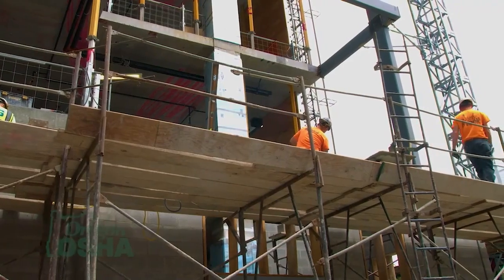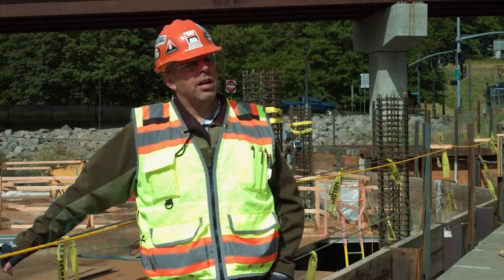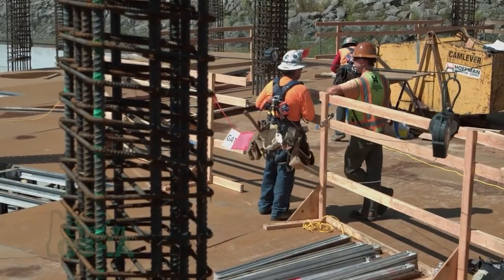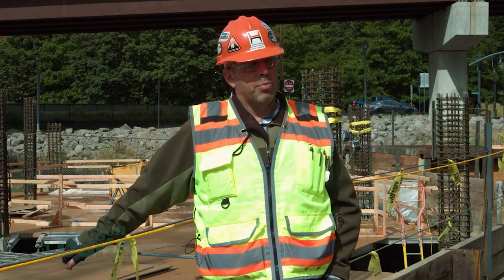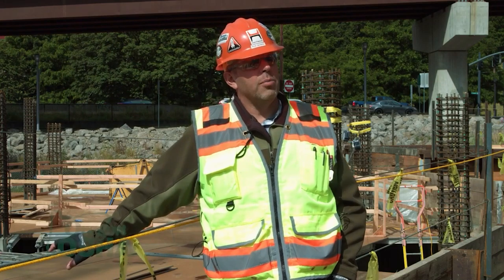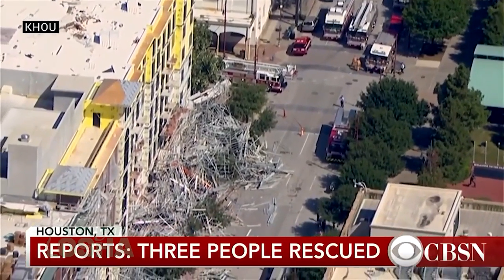You can use scaffolding as a catch platform. I don't do that as often. We will default towards a guardrail system if we can. One of the most important things, paramount in scaffold operations, is proper employee training. And I mean proper employee training beyond just a red tag or a green tag hanging at the bottom of the scaffold. Some of the biggest incidents in our industry are scaffold failure.